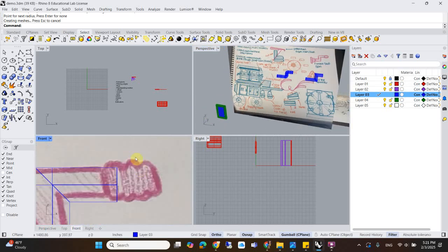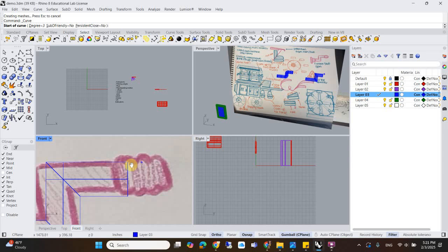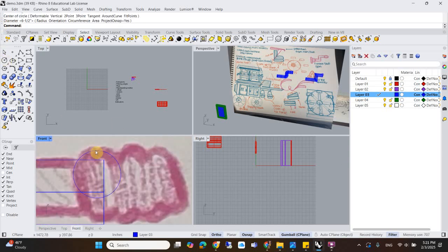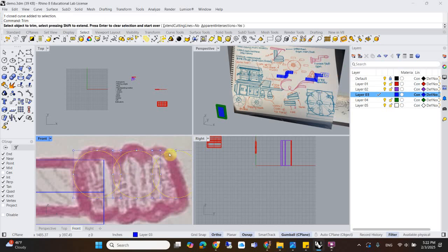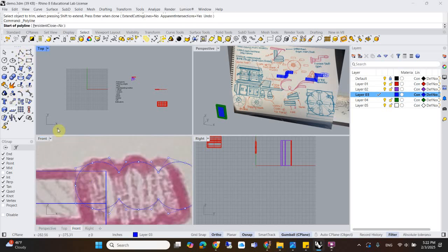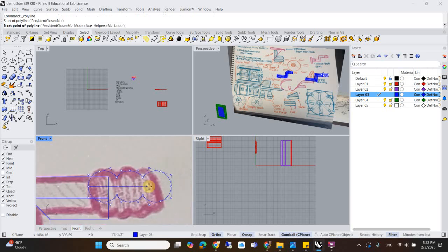And then for a revolve, right here, I'm tracing the outside of this, and this looks like circles basically, so I would just draw it as circles. You can draw one, and then if you copy it, you can keep them all exactly the same. And then I can trim all these. So I can select these, type in trim. I'm going to cut this off here.